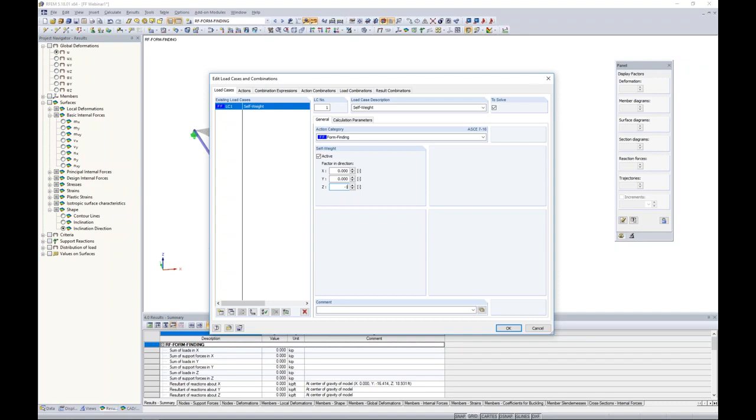Now, in reality, when we go out to the field and we pre-stress these elements, it's inevitable that self-weight will, of course, be included. So likely you're going to want to come in here, create a load case under the form finding category with the self-weight active in the negative Z direction here to account for that during that RF form finding process. We didn't do that, but now we can account for that with this load case. Now, any other loads that are available, again, pneumatic structures, we'd want to put them under this form finding case.